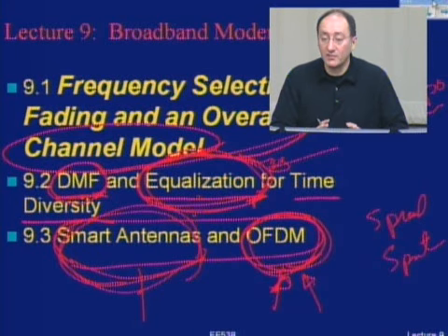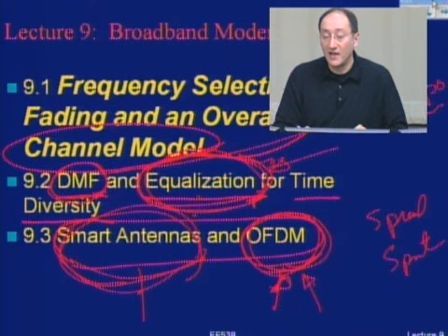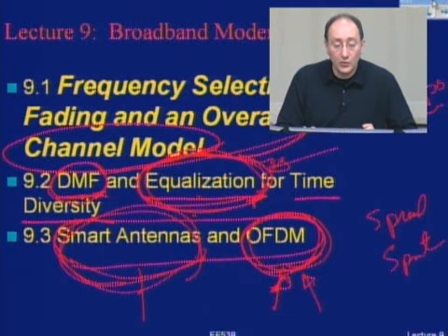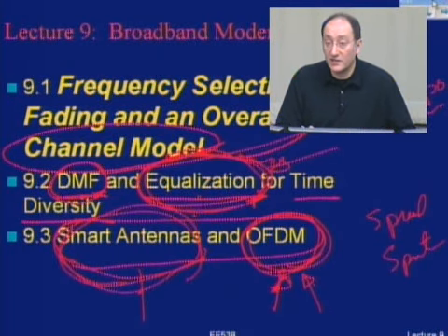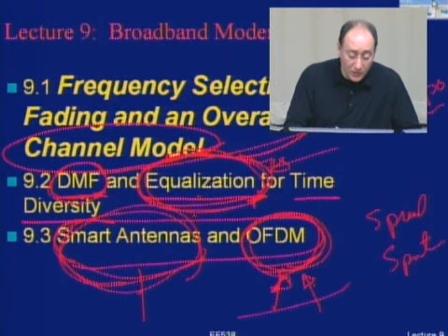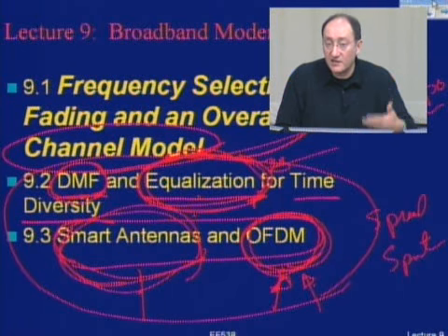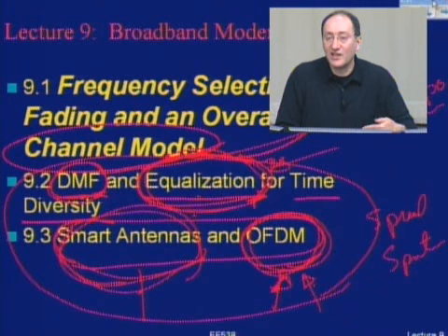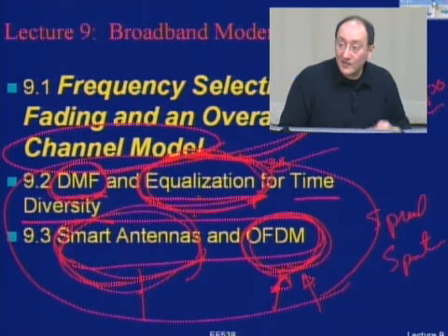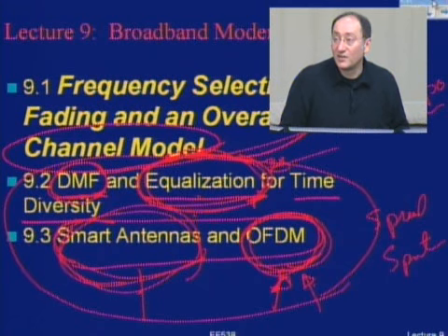And I want to give you some intuitive understanding of this and how they emerged, and how they provide diversity, really. Basically, all of these techniques provide diversity. The type of diversity that they produce is sometimes referred to as implicit diversity. Means diversity which exists inside, or in-band diversity, inside the signal, as opposed to explicit, like antenna diversity, okay?